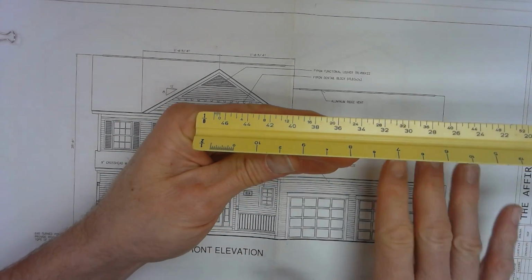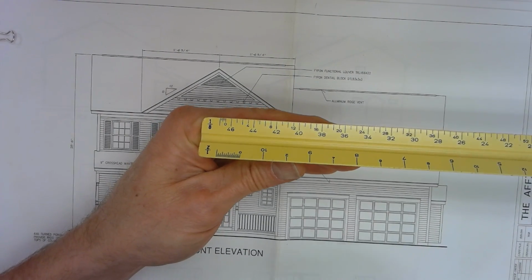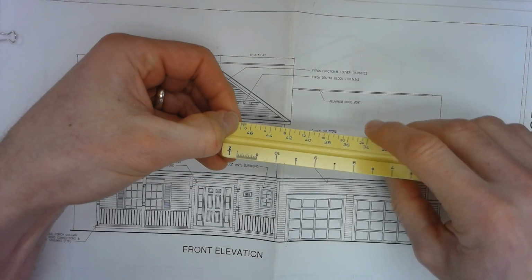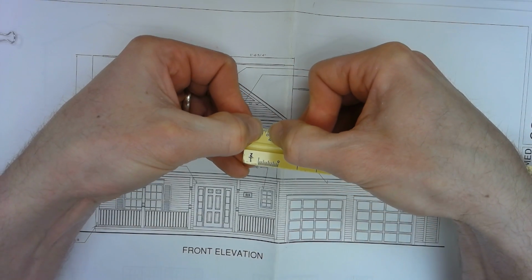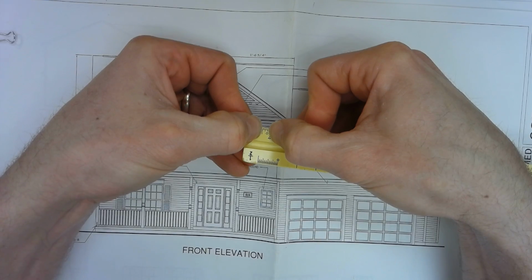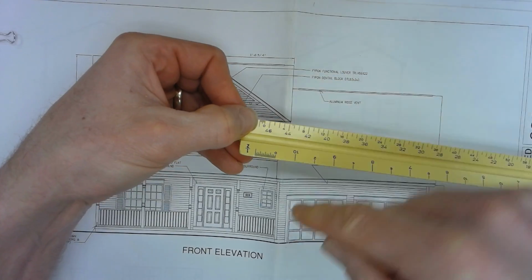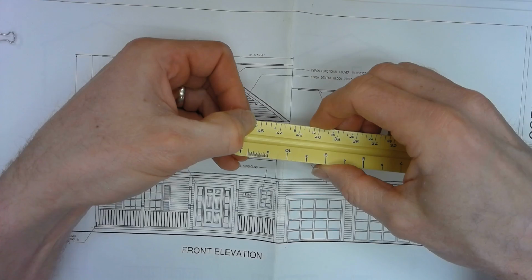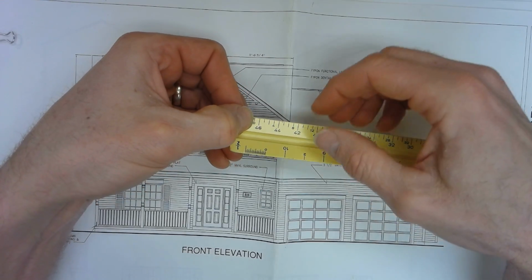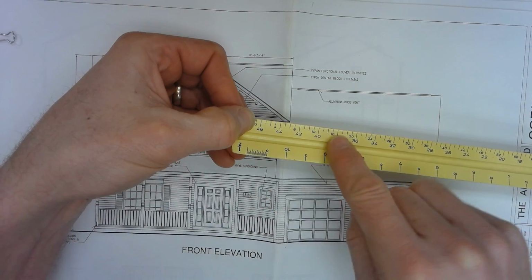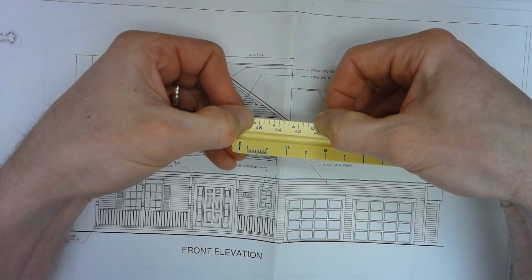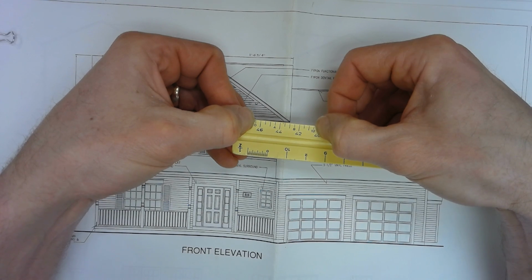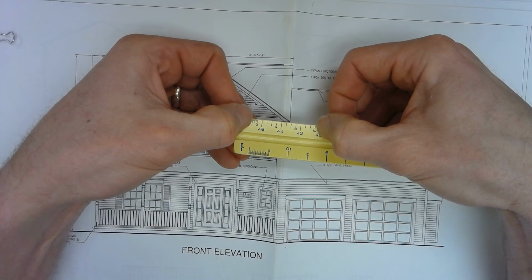We said that this drawing here is 1/8 of an inch equals a foot. So what they're telling you now is that you can see 1/8. They're saying from there to there, that distance between my thumbs is 1/8 of an inch, and that equals 1 foot on this drawing. So if I want to start measuring something, I would start at the 0, and I would count the smaller numbers. I'd count out the smaller ones, 1, 2, 3, 4, 5, 6, 7. So that right there, from my thumb to my thumb, that represents 12 feet. If I had to know how many inches there are supposed to be, I could count up over here.